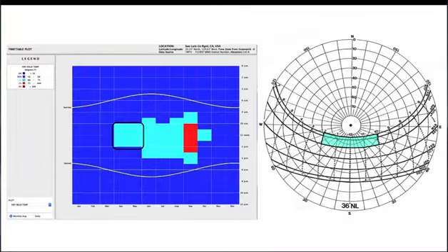And what this is going to do is tell us when the sun is anywhere in here, we want to make sure that we're not shading, or we attempt not to shade the building because people are already comfortable. So we're going to go through this process. This is the winter sun path chart. Now we're going to move to the summer sun path chart.